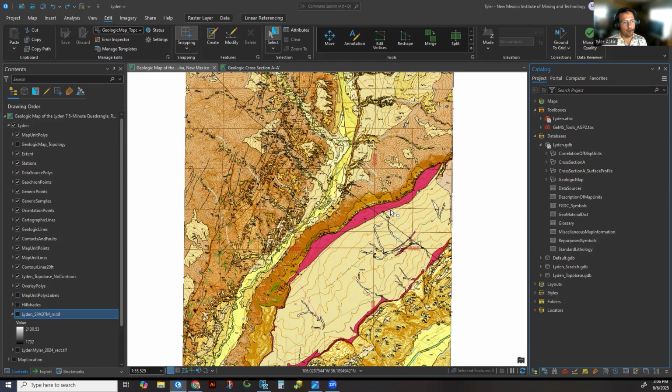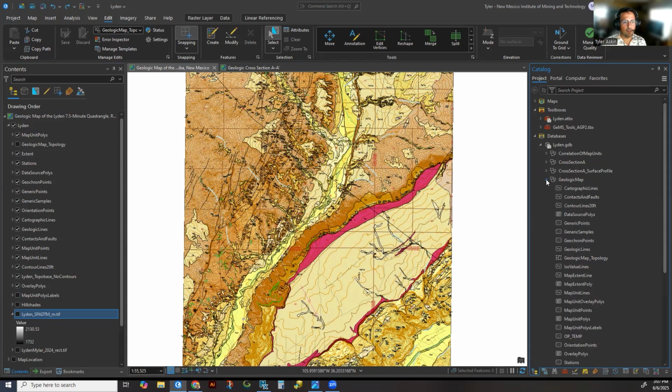The tool will not distinguish any of these points, so it will put all of them on the cross section. If you have a lot of points, it can get really messy and you'll have to parse through them and figure out what you want. So a little bit of planning ahead is useful when preparing to create apparent dip markers.